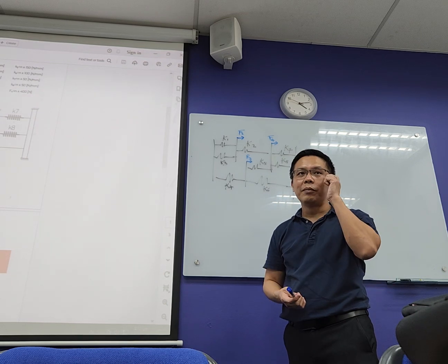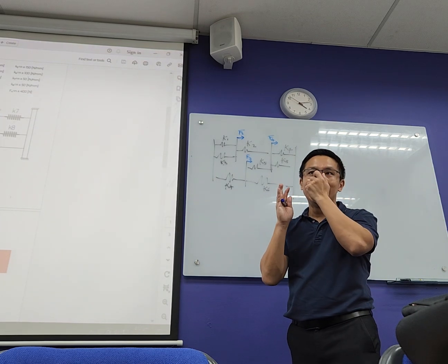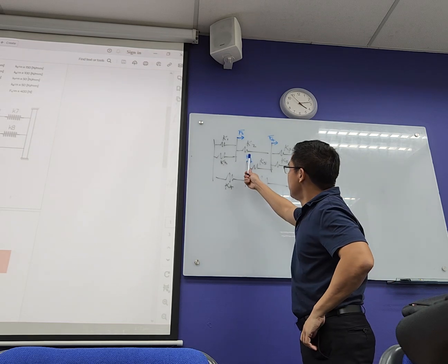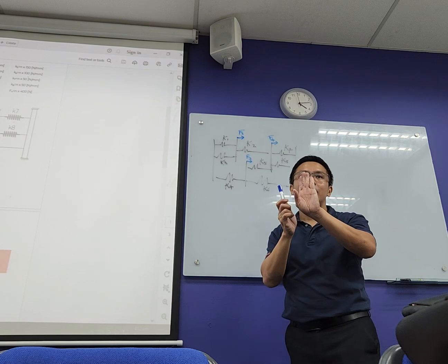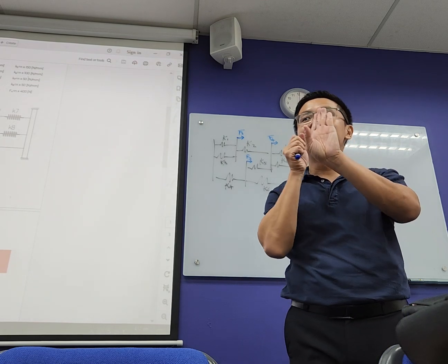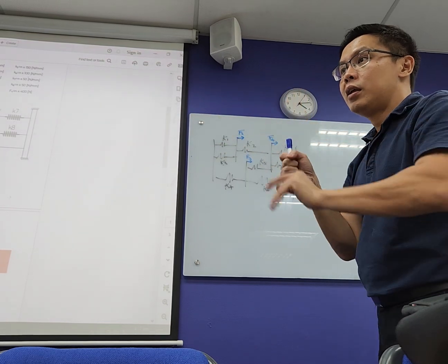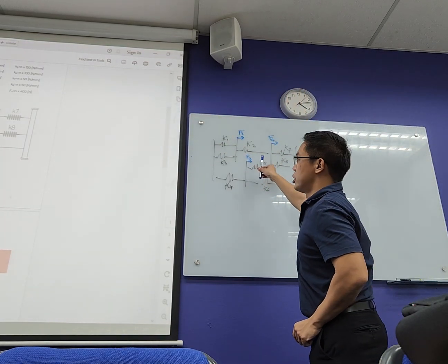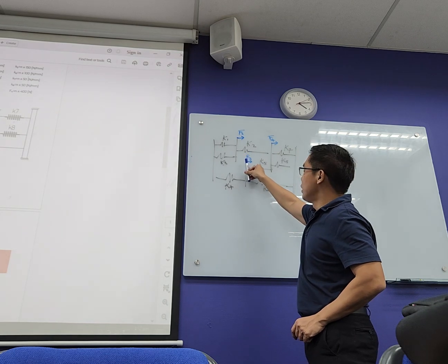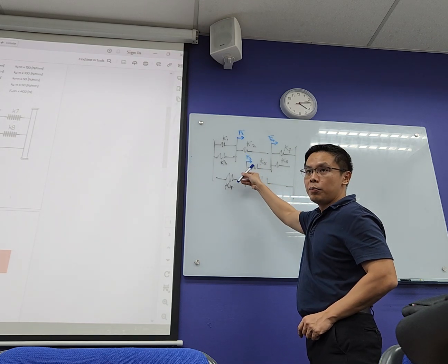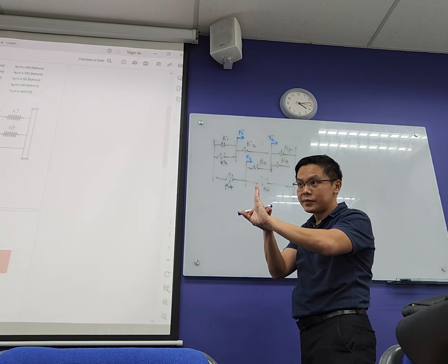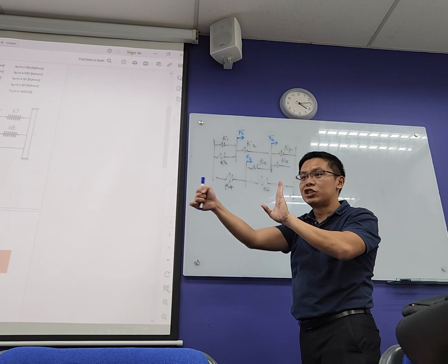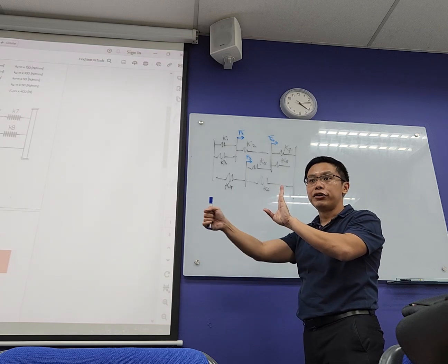the connection is the same. Now, to put it in a finite element perspective, this is a rigid bar, and I'm only giving it a displacement, so you only have one degree of freedom. It can only move in one direction. This whole thing can move in one direction, and it doesn't rotate, because if it rotates, I need to have a rotational degree of freedom. It only moves in a translational degree of freedom.